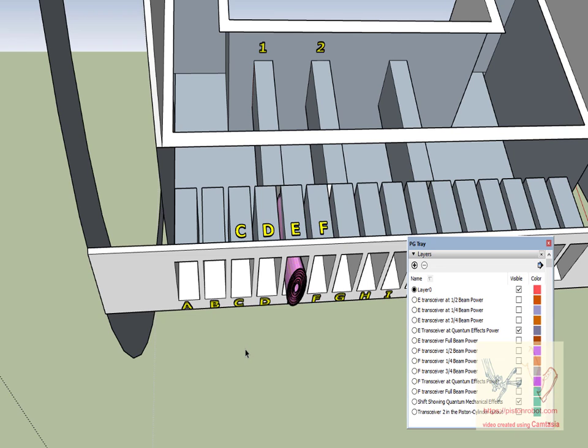But if an event is planned, then the city is going to have to make some plans. Let's say one of the plans is sewerage, because when all these people show up at the stadium, they're going to generate a certain amount of sewerage flow that is in excess of what is normally present at the city. So the city will have to plan to have perhaps extra chemicals on board at the sewage treatment plant, or perhaps extra filtering capacity or extra people. And so the city would want to know how many people are going to show up at the stadium.